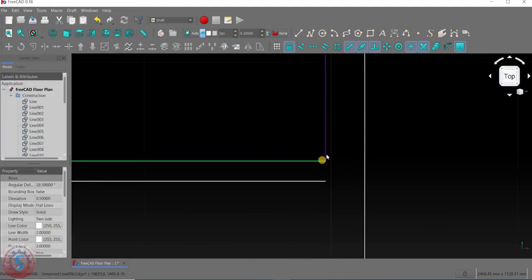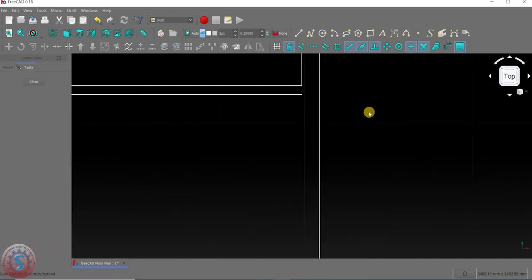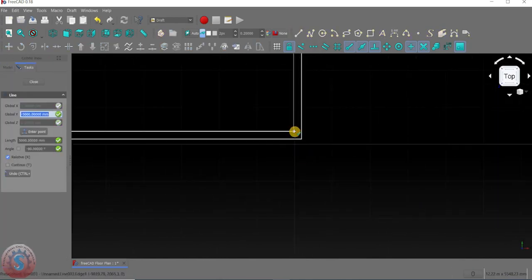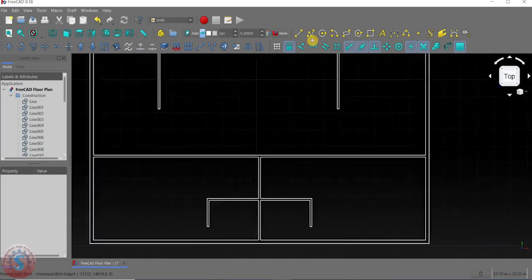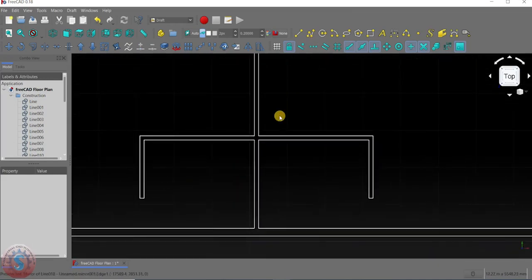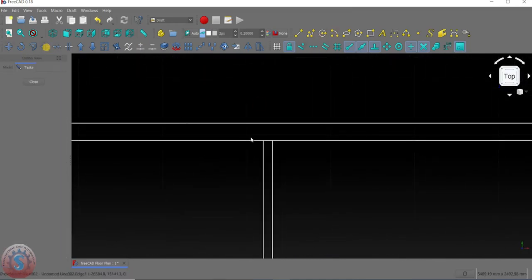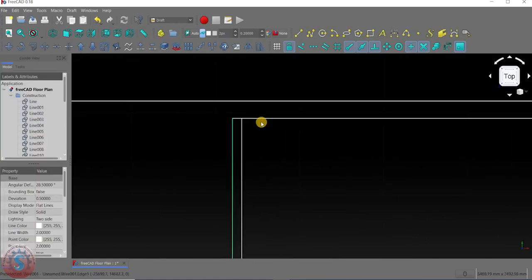Select the trim and select this and trim, and you want to create the line over here, and you can observe I am creating the line, first point and the end point. The line is also created, and where the trim is required, this is okay. I want to trim here and go into the trim option and select this line and select this, and I'm going with trim again,